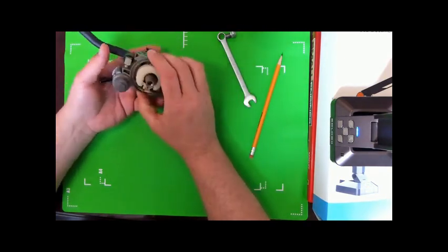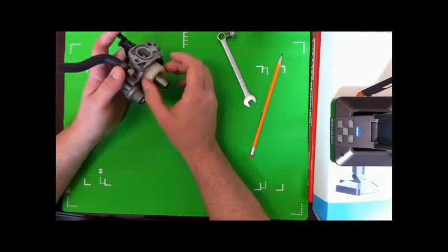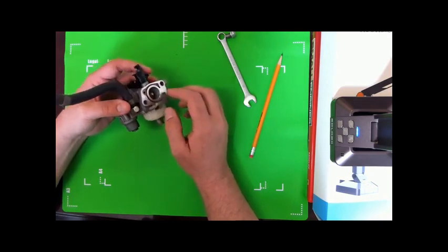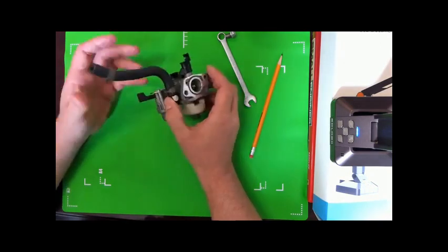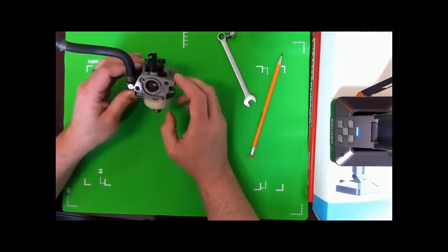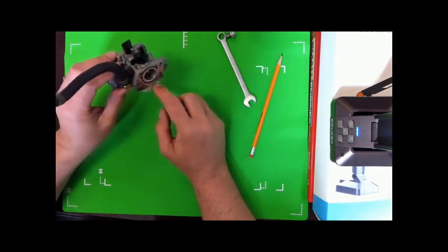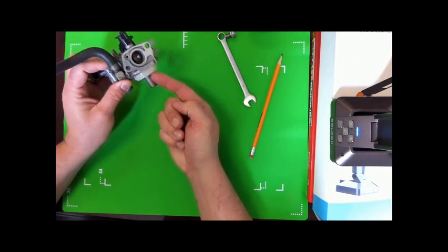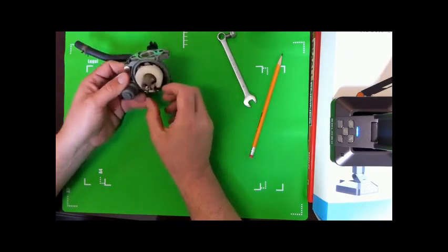Next, we'll see more of the inside of this carburetor. We can see this white plastic piece here. This is going to be our float. This is going to work very similar to the float in the back of your toilet, actually. As this moves down like this, the fuel level is low, and the fuel would, as I push up, be raised, and it would actually shut off the flow of fuel.